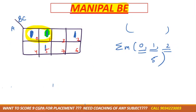Now next we need to understand how we can do the naming of this. Suppose it is 0 1, as I told you, 0 0, 0 1, 1 1, 1 0. So I can mark it here as B bar C bar, B bar C, B C, and B C bar. This one would be A bar and A, correct?